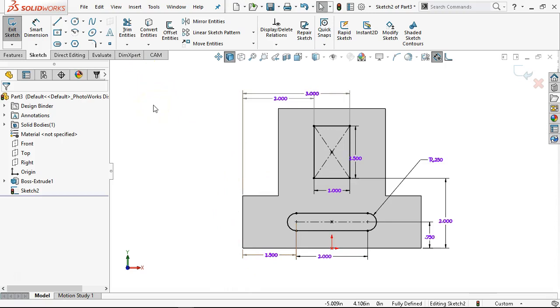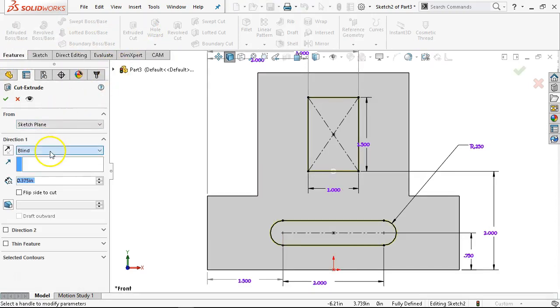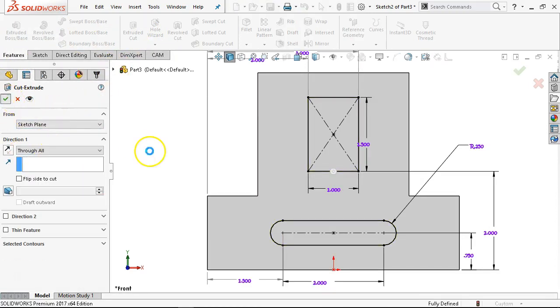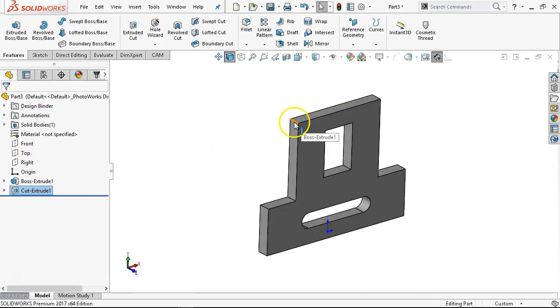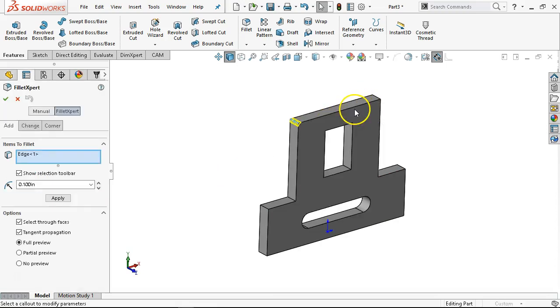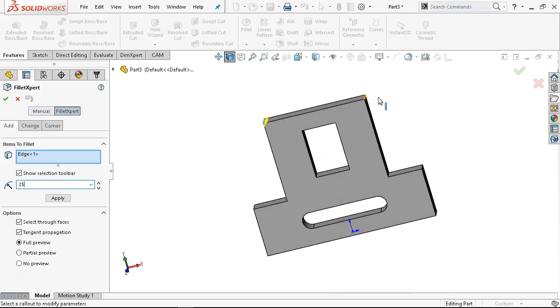All right, so at this point I haven't applied any sketch fillets, and this is a pretty good example place where I don't really need them. If I rotate over and find one of the fillets, the first time through, it's going to give me just the dimension 0.25, not 25.